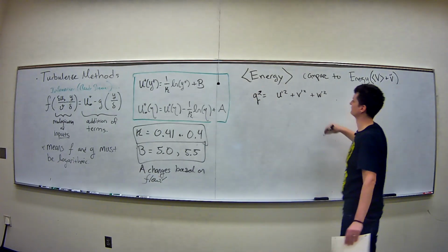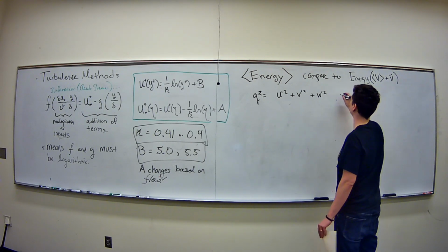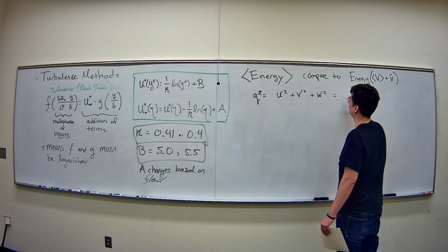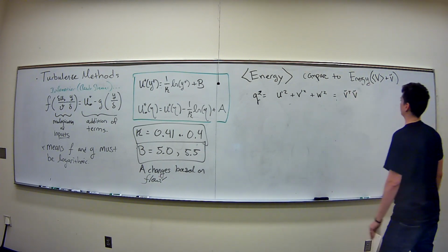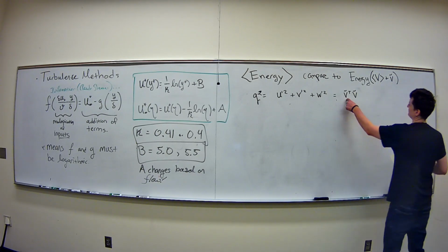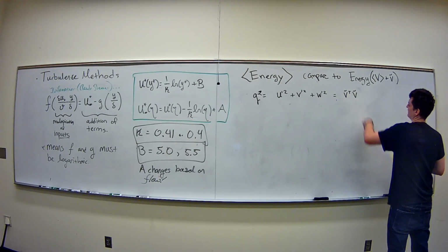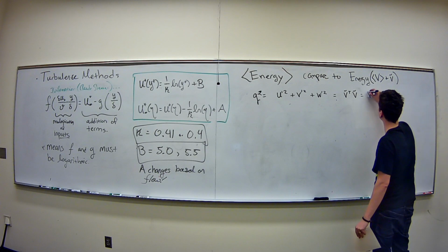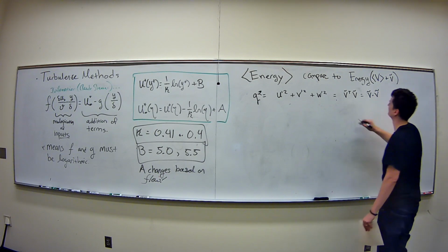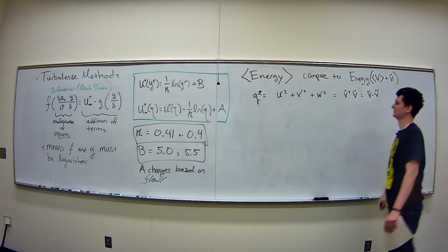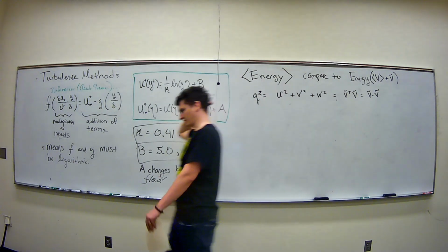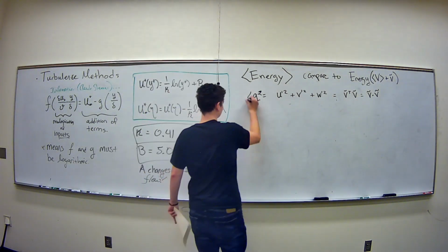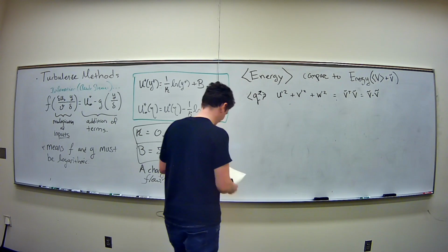So then this is this variable q, which is a dot product of the two vectors. So q squared is really a fluctuation transpose times the fluctuation, or just the dot of them. This is very important. So this is the mean turbulent kinetic energy, and we track the mean turbulent kinetic energy.